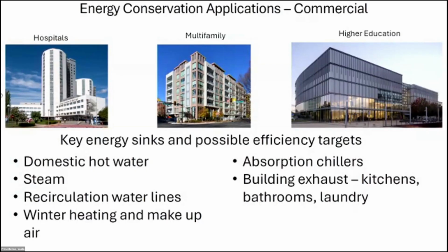Then on the modulated building exhaust side, the demand control response side of it, I work in a lot of central kitchens, bathrooms, and laundry systems. So multifamily applications, multi-story buildings where the domiciles are very, very similar in layout, and maybe your laundry systems are all stacked on top of each other, pulled over to a central trunk line with a fan on the roof, systems like that.